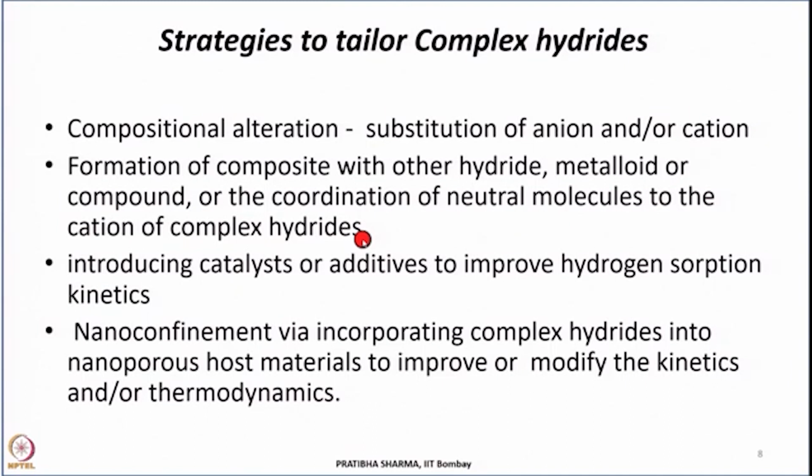There is a possibility of tailoring the properties by introducing catalysts or additives so as to improve the hydrogen absorption and desorption characteristics or kinetics. Another strategy could be confinement, incorporation of these complex hydrides into nanostructures, into nanoporous host materials, and that has also been found to improve or modify the kinetics or thermodynamics or both for this class of materials called complex hydrides.